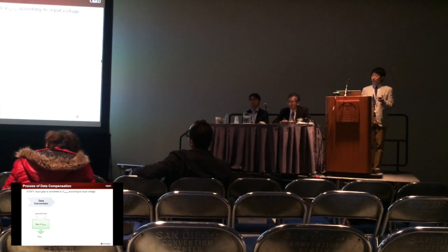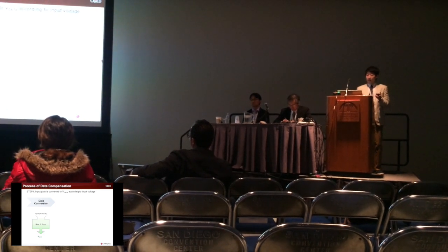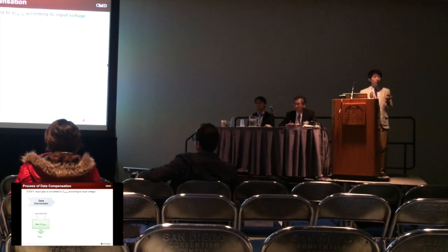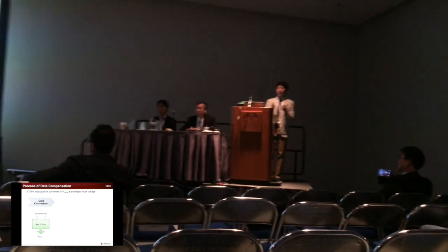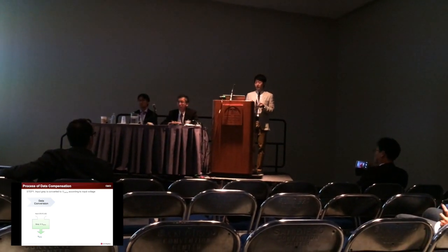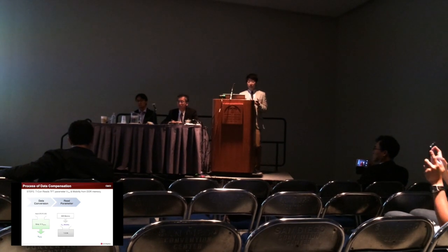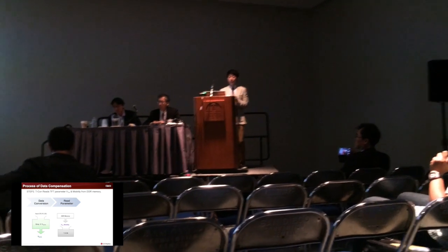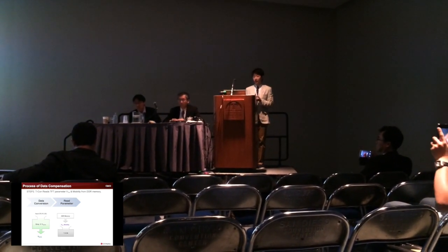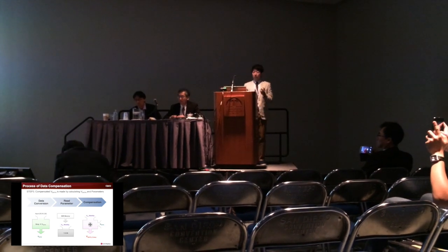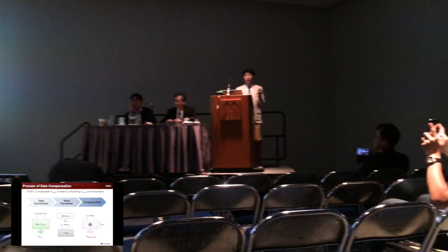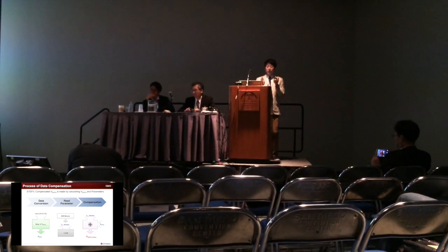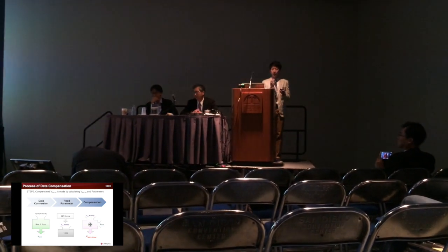On this page, you can check the 3 steps of the data compensation process. First is data conversion. Input grade is converted to V data according to input voltage. Second is read parameter. In this step, the T-con reads TFT parameters like VTH and mobility from DDR memory. Last is compensation. Compensated V data is made by calculating V data and parameters. Through this process, you can remove the variation among TFTs.